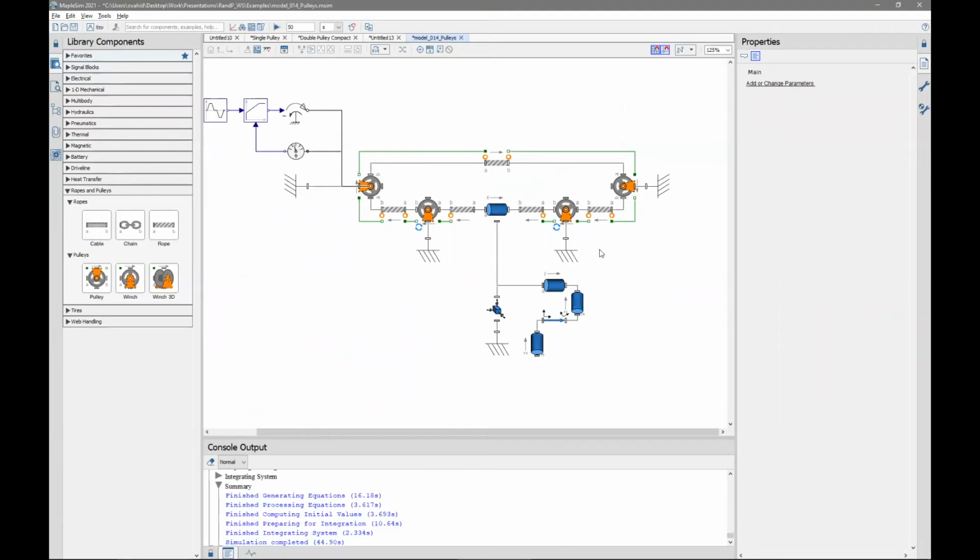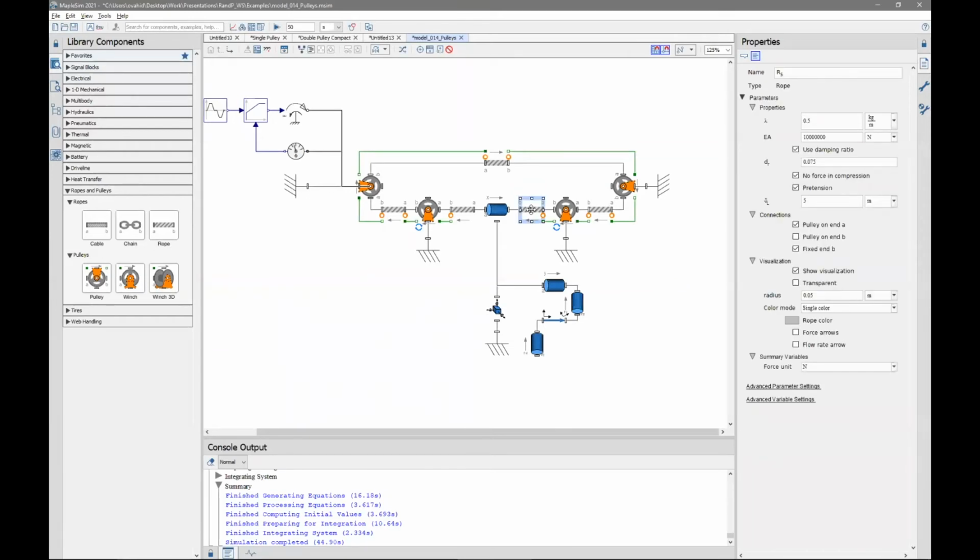One thing to notice from this, as we have looked at the ropes, the initial length of the rope is selected as the two endpoints at the start of the simulation. So sometimes that does not create enough tension and causes a lot of sag. So we do have the option to apply pretension, which is selected for this system. We want everything to have higher tension so that the hanging body does not sag too much. So here we can use pretension.